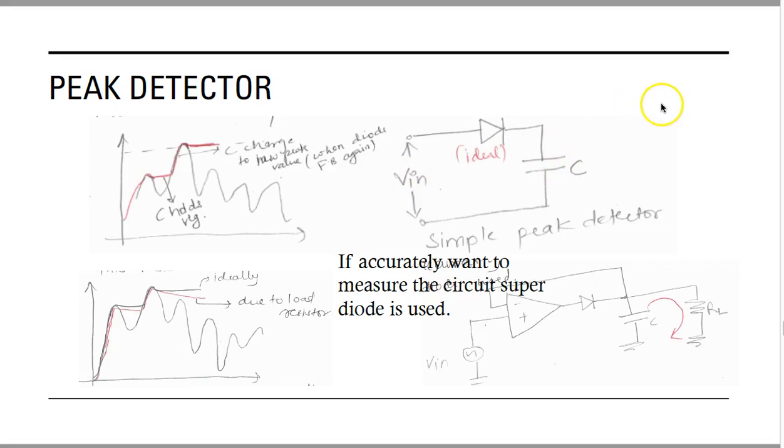And as you get the new Vin voltage, the capacitor holds the value of the new input voltage. So here you have this signal, and this is the peak of the signal which is being detected. Here you can see, for example, that your input voltage has gone down, but this capacitor will hold this value until a new value which is greater than this is observed.